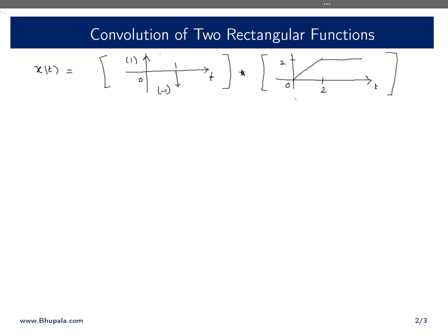As said earlier, we have a link where we have evaluated the derivative and integral of the rectangular function. So this finally boils down to this: here we have a Dirac delta function convolved with this function. Now we will use the distributive property of the convolution, and hence the convolution of this Dirac delta function with this whole function will give you the same function, because convolution of any signal with Dirac delta function is the same signal.